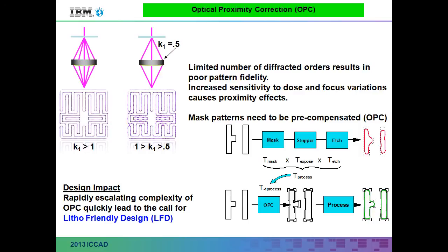these proximity effects. And the one good thing is that they're very systematic. You can calculate exactly how these things behave, and that's what led to the introduction of optical proximity correction. And we basically built mathematical models of how features are distorted on the wafer as a function of these diffraction effects. And while we were at it, we threw in some other effects like what happens in mask making, what happens in etch, and sort of captured all the systematic process inaccuracies.